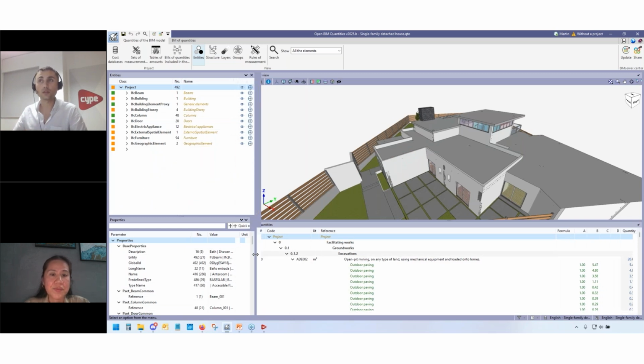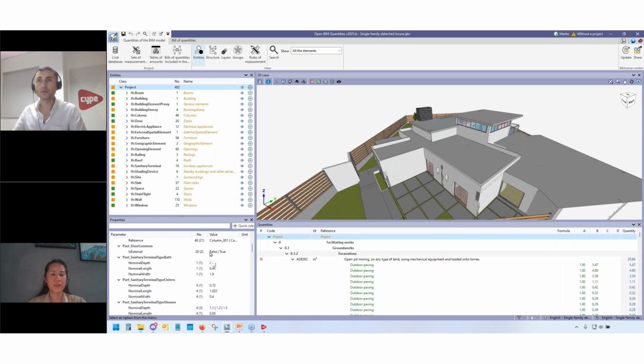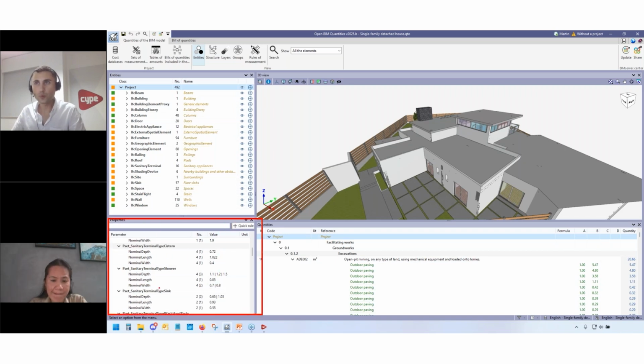It's interesting to get familiar with these concepts. Here in the properties panel, down here, we have properties that come with the actual modeling of an element. When we model a wall, you're modeling a rectangle that then becomes a prism, with an area and the volume and so on. All those properties, quantities, are present in the actual element. So the properties panel displays those quantities.